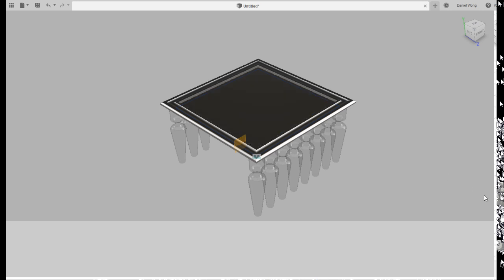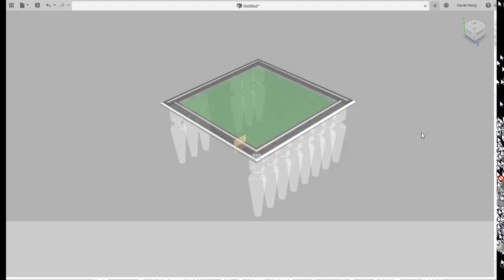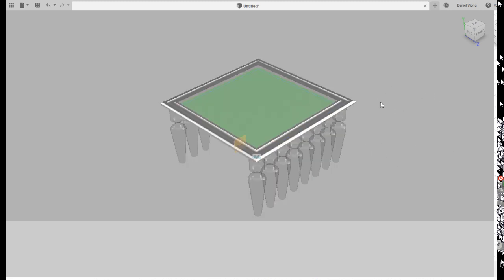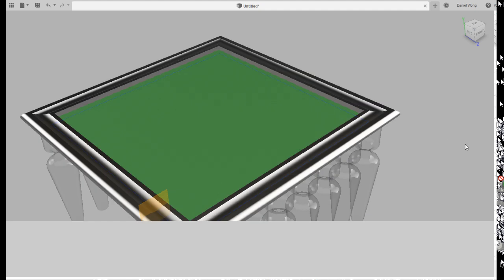Okay? What we're going to do is look for, I think it's not plastics. It should be paints. Yes, we're going to paint our color. And we're going to go with a powder coat rough. And I want green in this case. Now, you might need to download it, so there might be a download button there. Just hit the download button. In my case, I'm going to go with green. And all you need to do is, again, click and drag it onto that surface. And now we have the famous jade green texture.